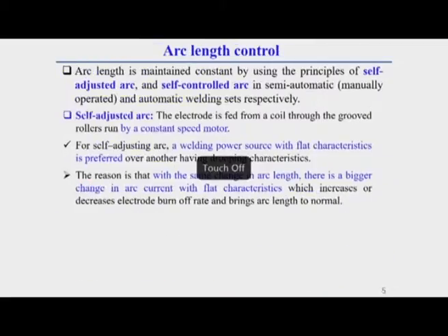And the torch used in this process should also keep some distance from the workpiece. That distance should also be 10 to 12 millimeter. Why should the arc and torch be kept a little away from the workpiece? Because otherwise the arc can damage things. Once we keep this distance around 10 to 12 millimeter, there is less chance the welding torch will be damaged.